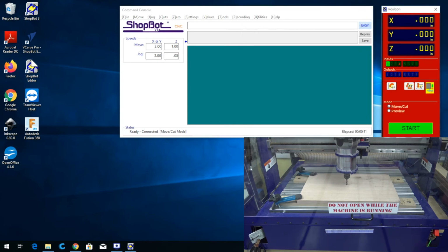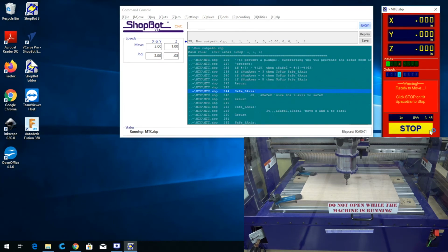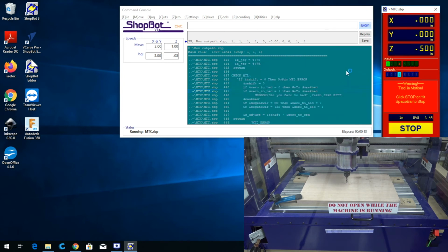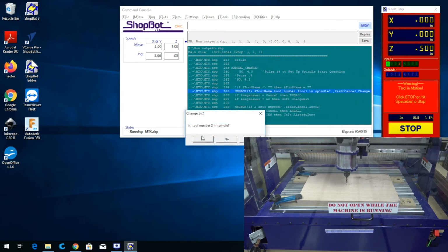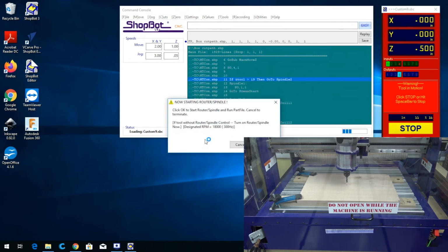Once you press Start, the machine will raise itself up 1/2 inch. This is to allow it to have free movement during the moving process. Note that while the machine is moving, I am unable to move my mouse from the Stop button. Once the machine is finished moving, several pop-ups will appear. Verify that you have the correct tool in, and the Z-axis is in the correct location, and then hit OK.